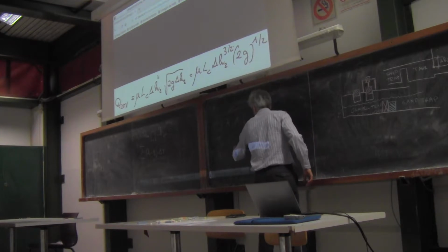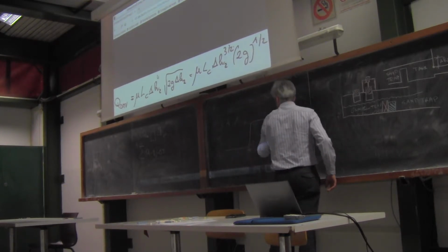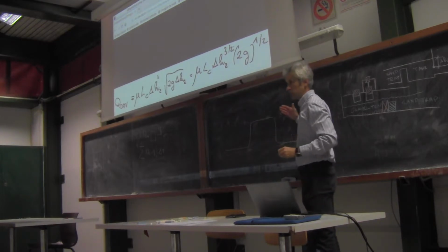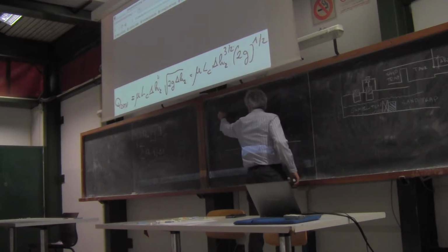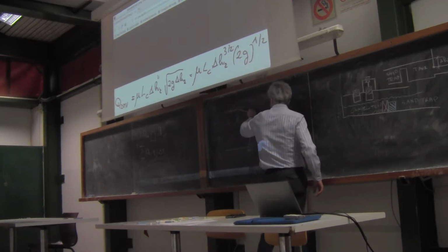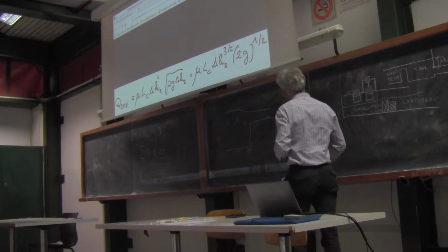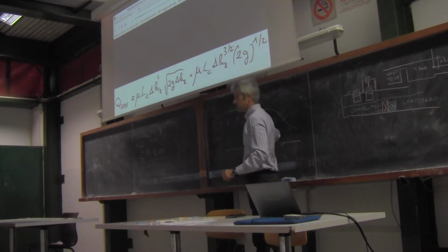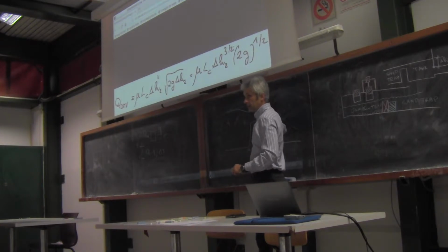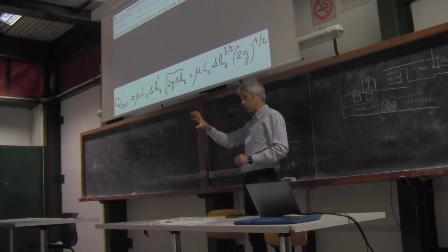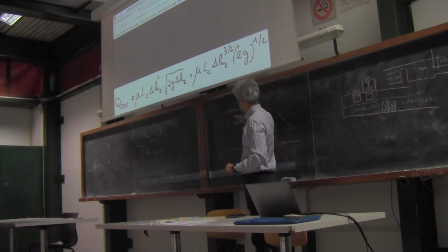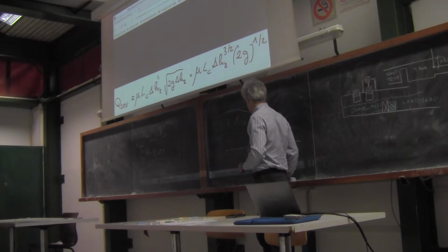Okay, so this is a spillway, very easy. This is a cross-section of a spillway, and the flow over the spillway occurs in this way. And in the proximity of the spillway, we have a lowering of the water profile, because basically the spillway calls water, and therefore the call of the spillway implies a lowering of the water profile.